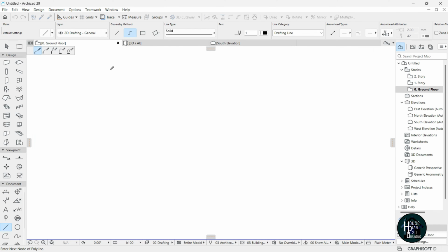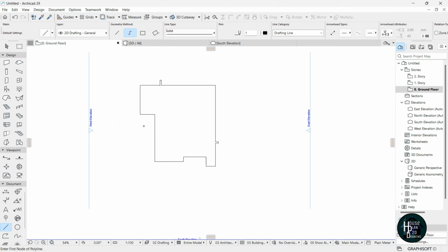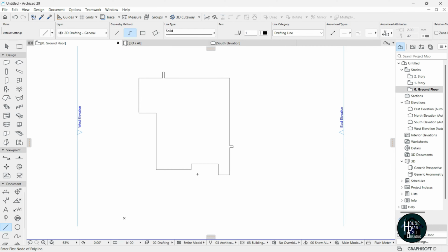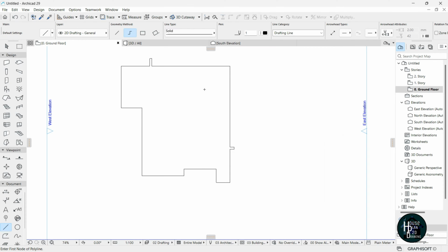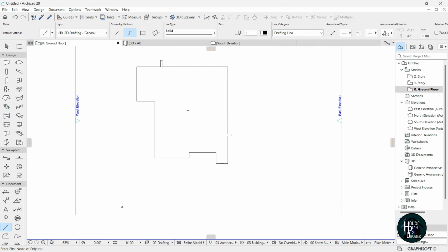Okay, just follow this arrow. It's supposed to give you 2225. That's very important. So just click here and just click back here. So you're going to be having the full external features of this particular design. Now the next thing I want us to do is to come and use dotted line to sketch out the passage area for this particular floor plan.